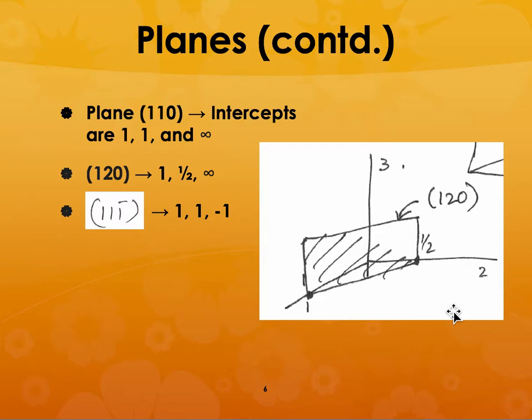And why is a plane important to know? I mean, why is this information important? It is important because many times, for example, if you are deforming a particular material like copper, which is face-centered cubic, there are certain planes and directions that are much easier to deform. So these planes help you to characterize the material.